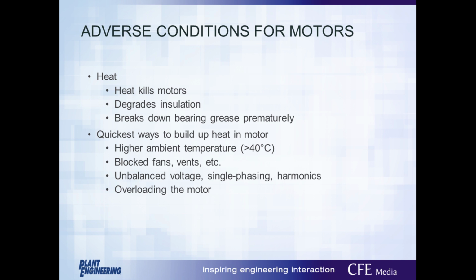Power quality is a very broad term, but some of the typical issues include unbalanced voltage, single phasing, or dropping a phase, or relatively close in proximity nonlinear loads that will lead to voltage and current distortion, known commonly in the industry as harmonics.